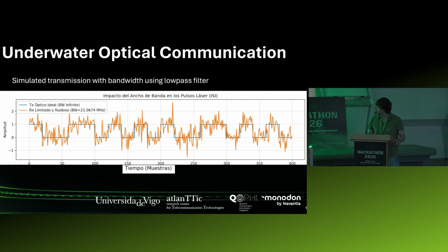Well, and for the modulation, we ran a random simulation of bits for our return-to-zero OOK. And there you're seeing, I think that's the point, yeah. This is the OOK modulation, and what you are seeing on the yellowish line is what we should receive because we are considering an additive white noise channel. We are talking about the noise later in the presentation, but we simulate the bandwidth with a low-pass filter, and this is what, statistically speaking, we should expect in the channel.